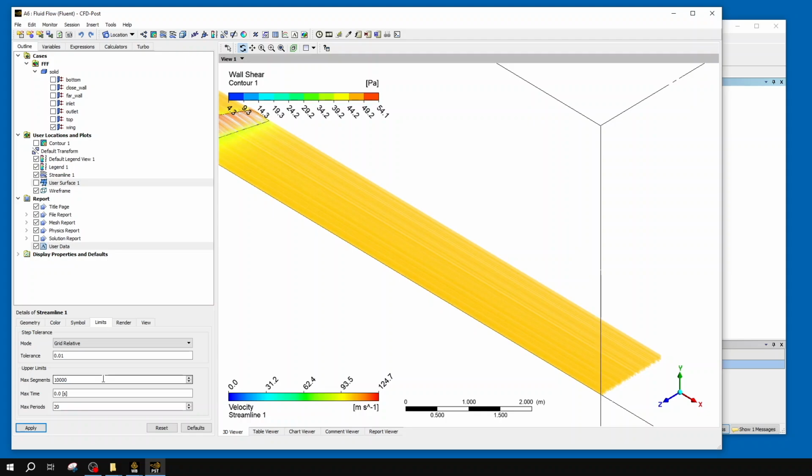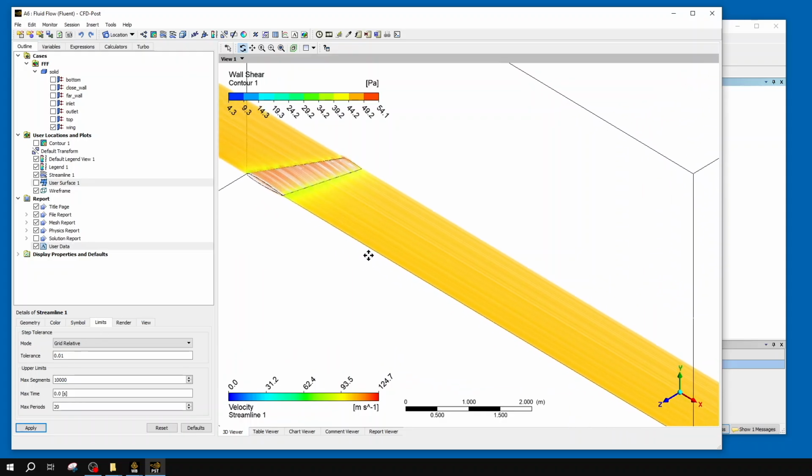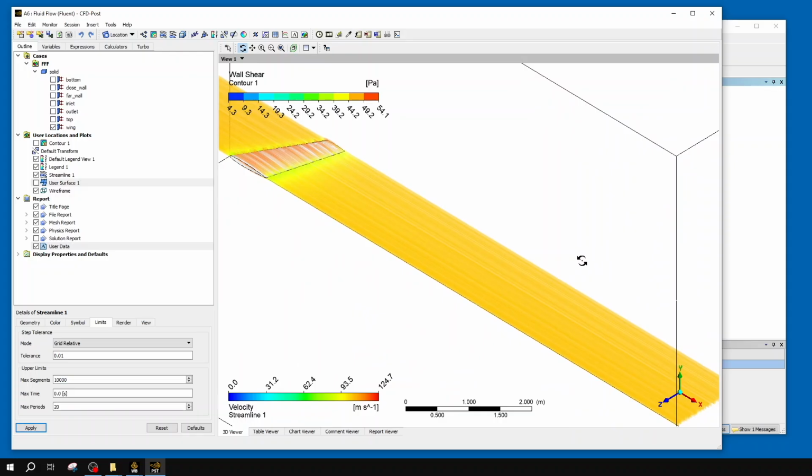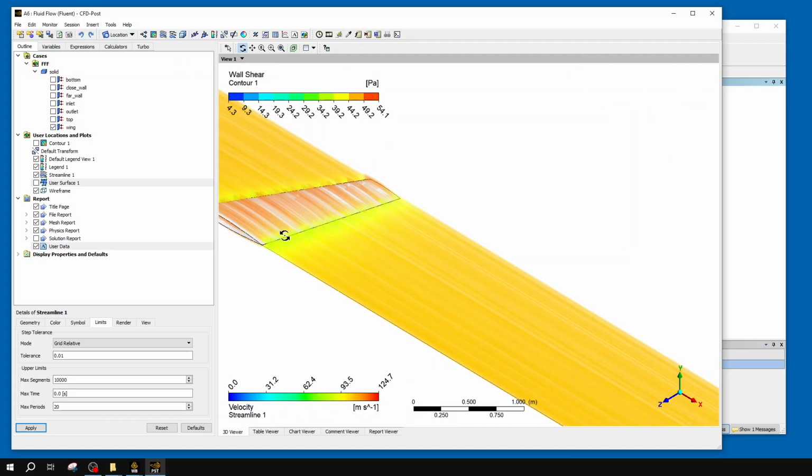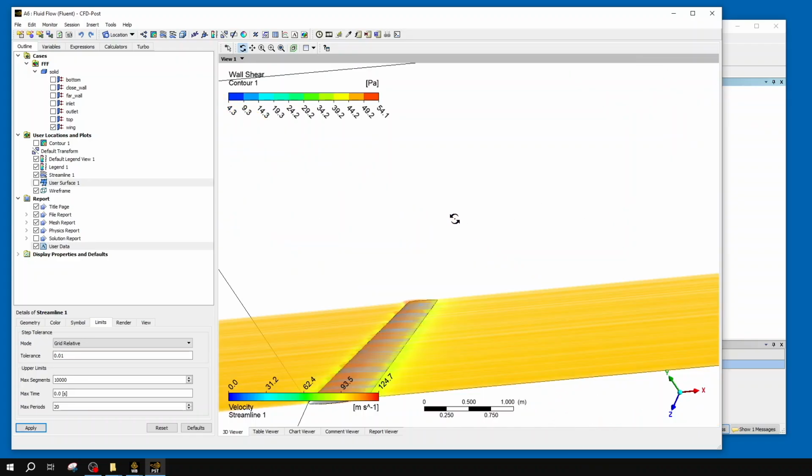And one of the things it does consider is the flow speed. So it won't necessarily directly cut the flow off here. It might have a weird looking pattern based on the speeds experienced at the wing, right? Maybe this stuff by the root slowed down just a tad more than the stuff by the tip.